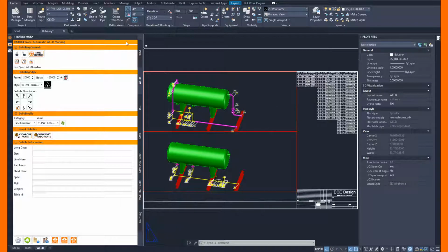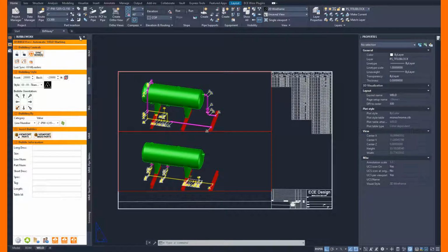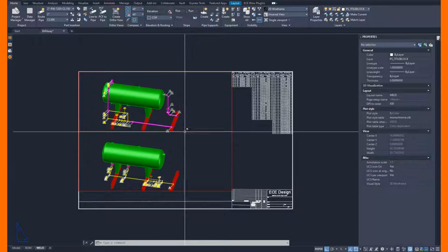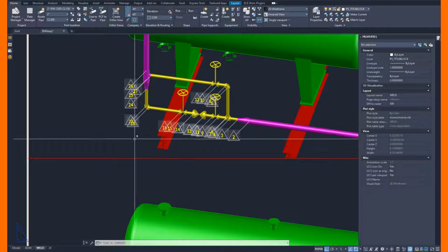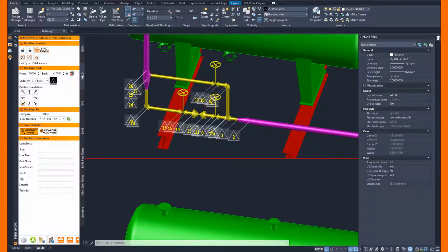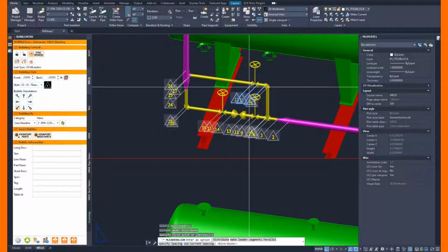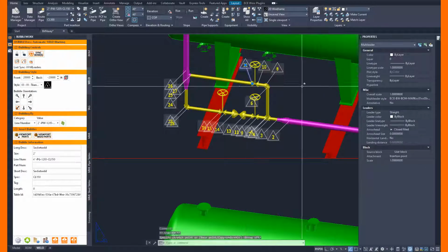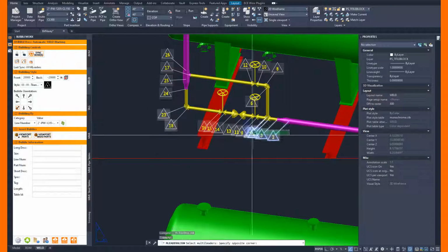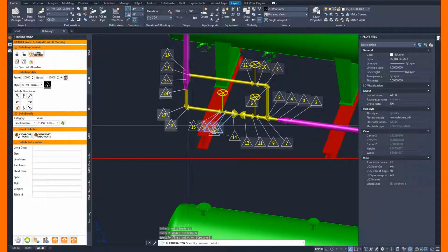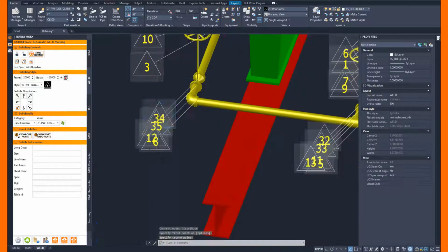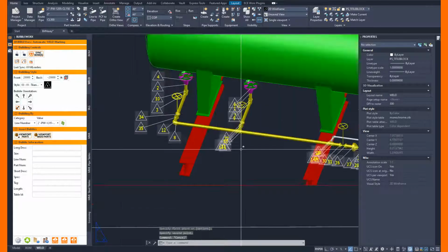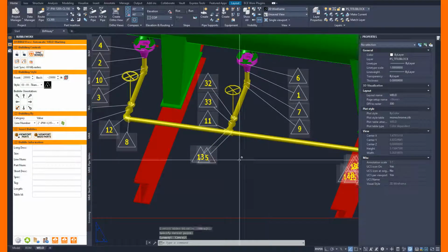Well, up until this point, the placement of the tables and the bubbles has been automatic. So I'm going to go ahead and dive into the bubble location and just start rearranging the bubbles. It's really easy to manage the bubble location. Just re-engage BUBBLEWorx and go to the control where we can place the bubbles with a basic stretch and orientation. This is pretty much an AutoCAD out-of-the-box feature, so with just a little bit of practice, users can place these bubbles in a location that is good for everybody to see,